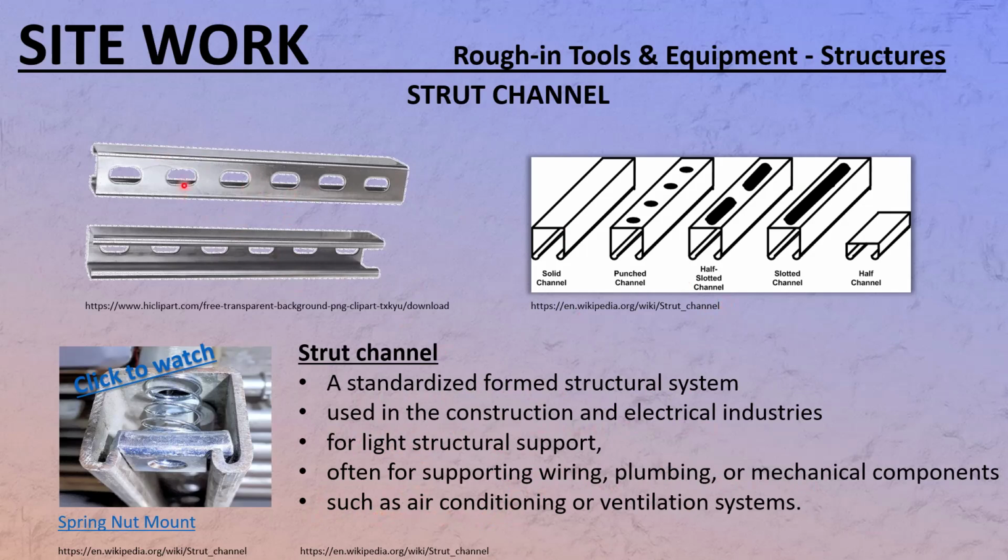Quite often, this is galvanized steel, so be careful when you're cutting using a blade, like a chop saw blade, to cut those. It looks like a stone blade. Sparks are flying. Whenever you have galvanized steel and the sparks are flying, toxic fumes are going to be produced. They are not going to kill you right away, but they are really deadly for you in the long run. So keep that in mind.